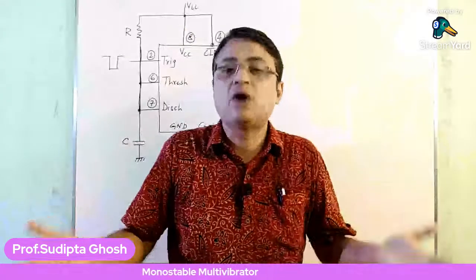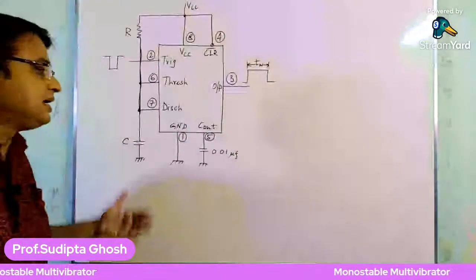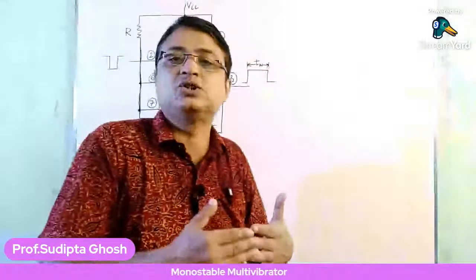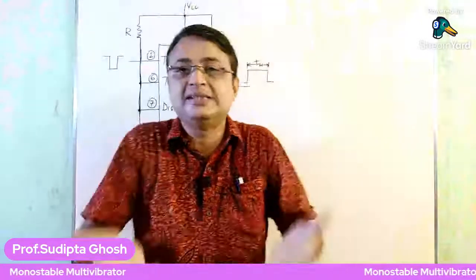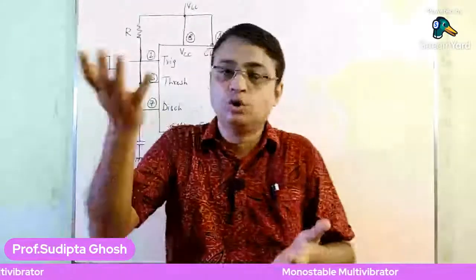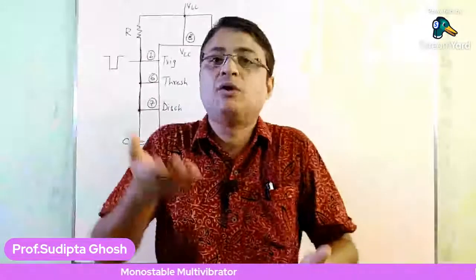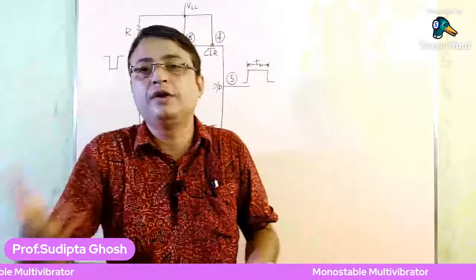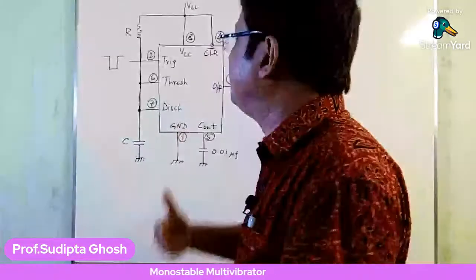How will it be possible? Now consider that the capacitor goes on charging. The value of the capacitor now increases from 0 towards VCC, or towards the value of 5 volts. After crossing the value of 3.4 or 3.5, that is 2/3 VCC, again the similar thing happens.